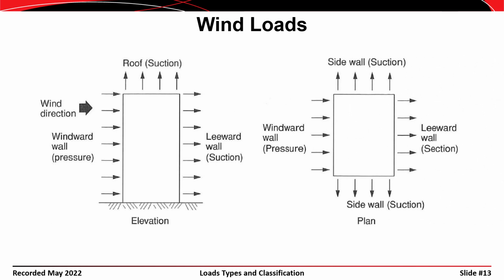Okay, if we look at the building in plan, then you can see the positive pressure on the windward face again. You can see the negative pressure on the leeward face again. But in this view, you can also see the negative pressure acting on both the side walls.